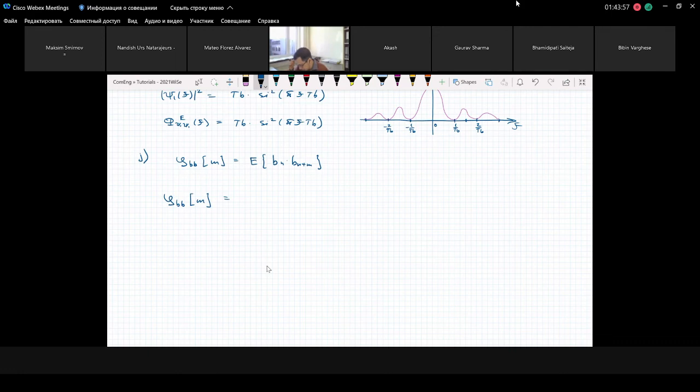Of course, as far as adjacent bits are independent, we simply calculate the second moment when the shift between original and copied sequence equals 0, and it equals the first moment squared when this shift is non-zero. We have such a traditional definition for the autocorrelation function, and if we just plug in all that we know, we get 1 over 2 for m equals 0, and we get 1 over 4 for m non-equal to 0.